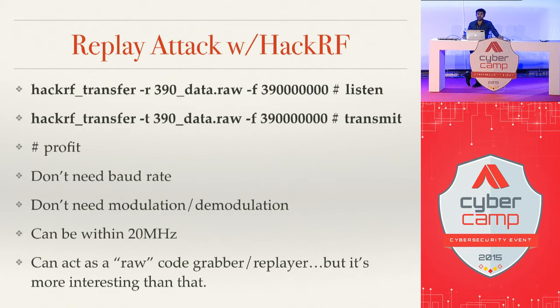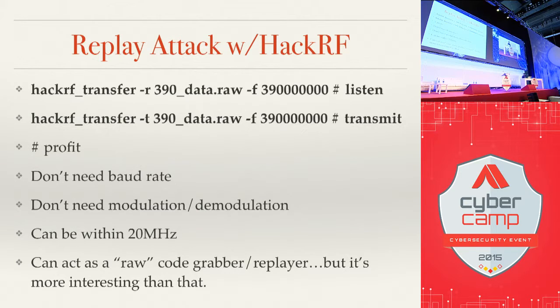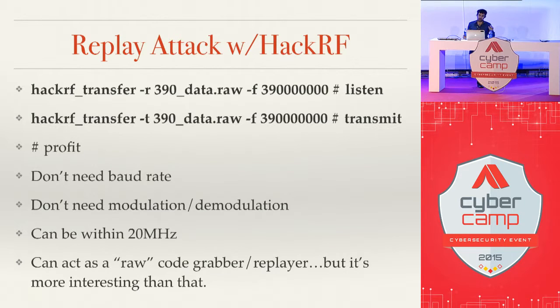Doing something like a replay attack is super, super simple. I mean, replay attack is probably the most basic of the attacks, but it's literally you can run a command to actually listen to, let's say this is 390 megahertz, and then to replay it, to transmit it. The cool thing about something like HackRF is you don't need to demodulate it, and you don't even need to know the exact frequency, you don't need to know the baud rate, you don't need to know the modulation.